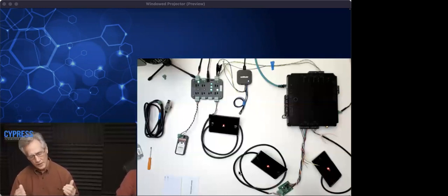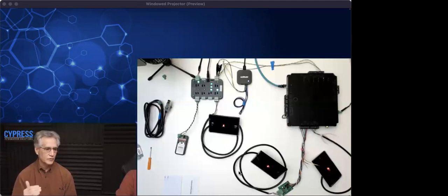So the best suggestion is to take this opportunity to replace the wire. That will future-proof it if you want to do enhancements later, because OSDP not only overcomes those basic vulnerabilities of Wiegand, but it offers so much more in scalability, having multiple devices, and speed. It can run 230 kilobits a second, which would not work at all over that 500 feet of Wiegand wire.